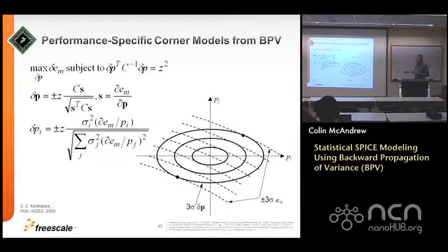If you think about it, what I'm showing here is two process parameters, I and J. The ellipses are intended to show 1, 2, and 3 sigma yield bodies here. And superimposed on that, in the dashed lines, I'm trying to draw constant contours for some electrical performance EM. So if you think about that, what you'd really like to do for the corners is you would like to